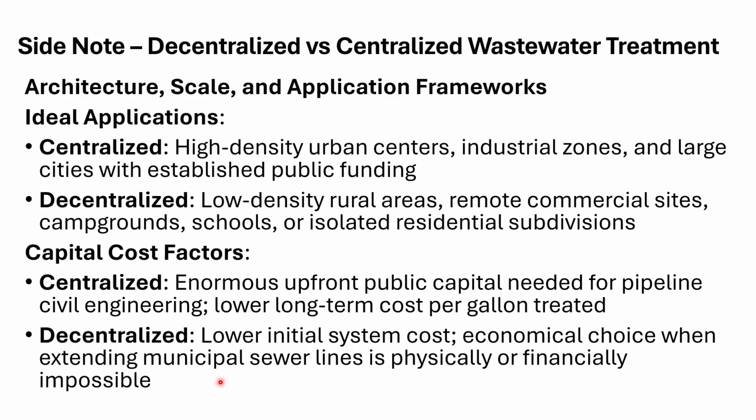They are looking long term at putting a sewer collection system out there, a wastewater collection system, and a plant out there. But that's a lot of money because those homes in El Dorado are spread out. Alternatively, they could wait for the city or county to extend wastewater service out there, but I don't see that happening because the amount of line that would have to be taken to get El Dorado's wastewater to the city plant or to a county plant near New Mexico 14 would cost way too much money. So for practical purposes, El Dorado is stuck with a decentralized system.